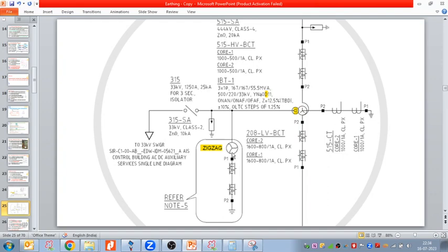So you only have to achieve one circle, right? And this is an interconnected star, so that's why we take this type of zigzag line, not a straight line, to represent this zigzag transformer. And further, as I told, we put the CT, called the neutral bushing CT, and it is connected to the ground.